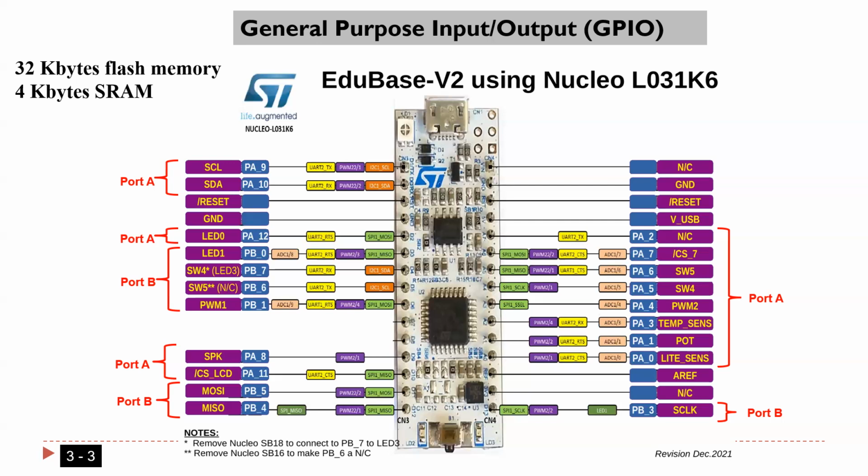Is that okay? Once you do the initialization, and this should be done only one time in your program, once you initialize the pin, input is going to continue as input unless you change the configuration. That's why you need to do the configuration only one time, right? So if you have a loop, you don't need to put it in the loop, because you just need to do it one time, okay?